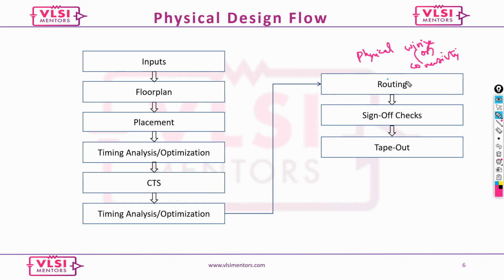And then once you are done with this, what is the goal? You might question me, Kumar, we talked about timing, congestion, and all that at placement, but do we really bother about them at CTS as well? Yes, the answer is yes. At each and every stage, you have to look at your timing, your congestion, and your utilization. What is your utilization, and what's your VT percentage, and then power, and all that, if you are working on a critical design.